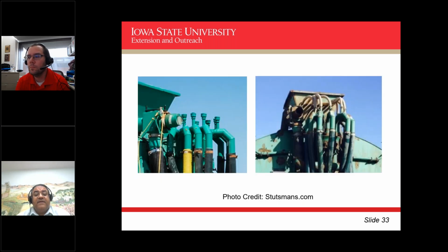In certain cases, folks have actually even taken the outlets and rerouted them back into the drum. Some folks have just taken the pressure plugs off of these vents. If you take all the restrainers off of these vents, then these vents will just gargle, and they'll throw some manure out of them once in a while. So the back end of your tank may look really dirty there right around the manifold. So some folks have come up with the option of rerouting those vents back into the tank itself.